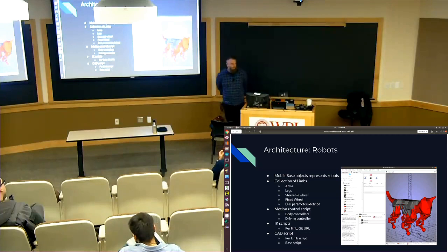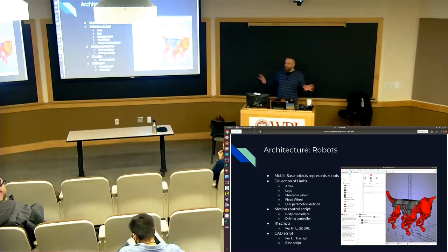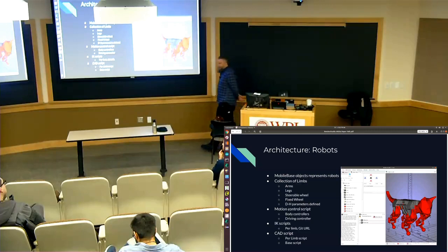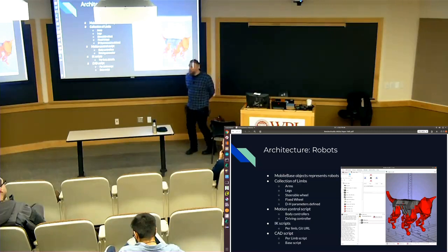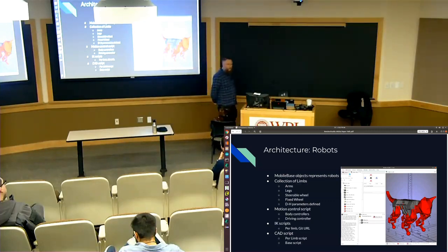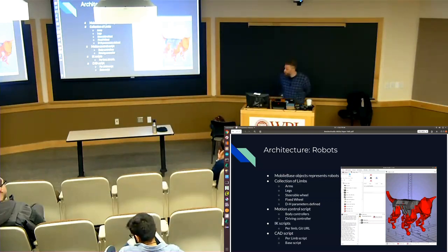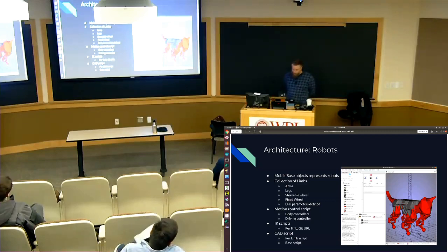So the script is defined by the absolute generic thing that you're doing: take the robot and move it someplace in some time. Every robot's going to implement that differently, so that isn't defined as a set of static code that you can't change. It's instead defined as a script that is hyperlinked using the XML that describes your robot in the first place.